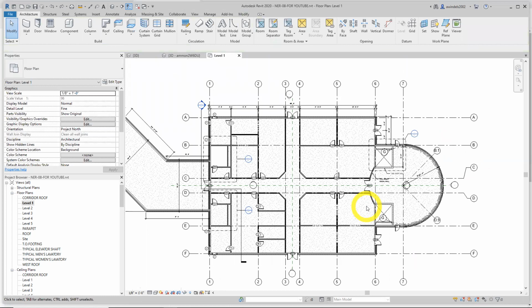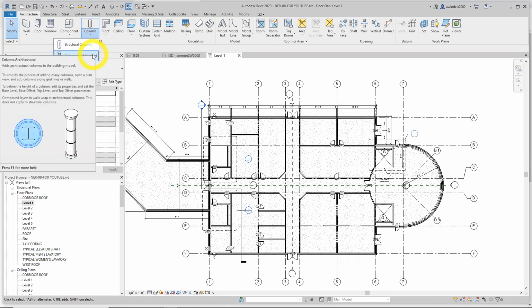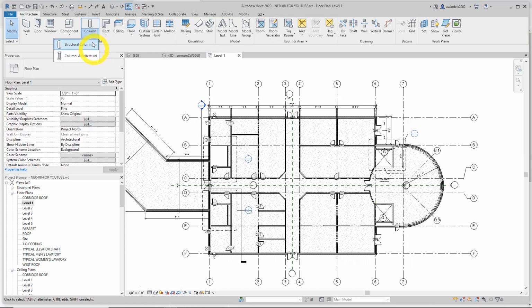We're going to add some structural columns with Revit, and generally columns are vertical, so in the Z dimension, elevation. There's structural and architectural columns. These ones, we're going to stick to structural columns for now. So let's stay on level 1 floor plan, and we're going to go to the radial entry east wing. We're here, and I'm going to go through this surgically because we have to add a lot of these structural components. We have to add them through families, so I'll go real slow through this.